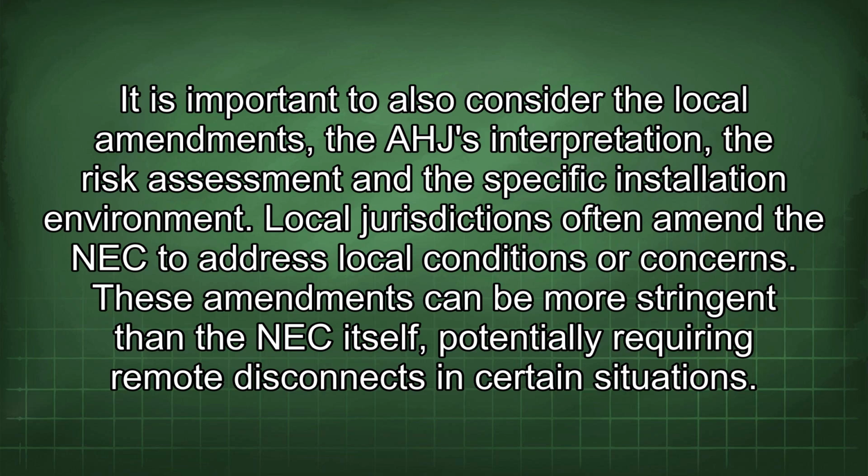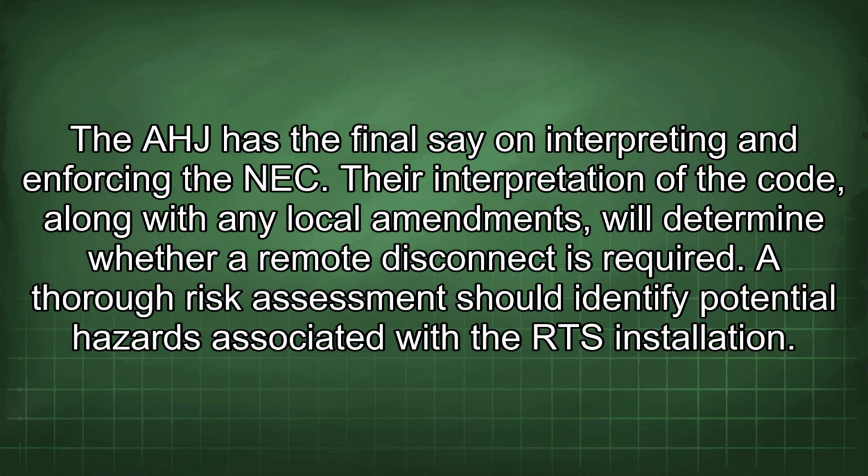Local jurisdictions often amend the NEC to address local conditions or concerns. These amendments can be more stringent than the NEC itself, potentially requiring remote disconnects in certain situations. The AHJ has the final say on interpreting and enforcing the NEC. Their interpretation of the code, along with any local amendments, will determine whether a remote disconnect is required.